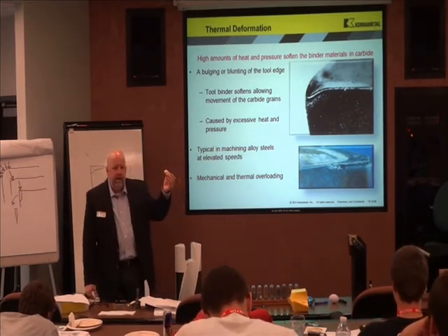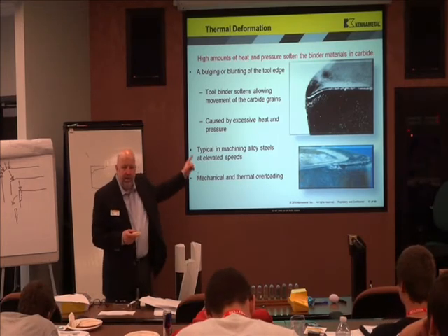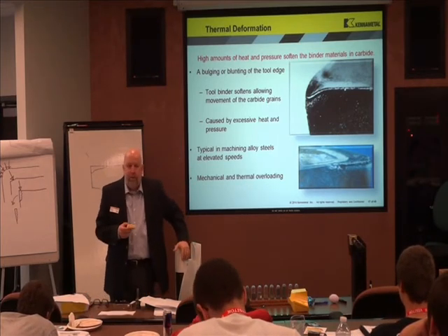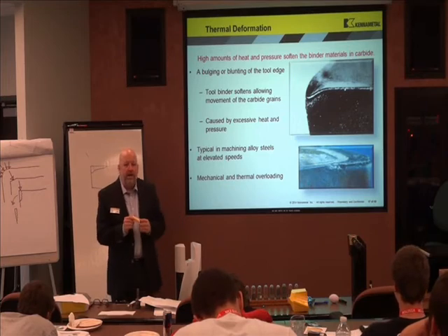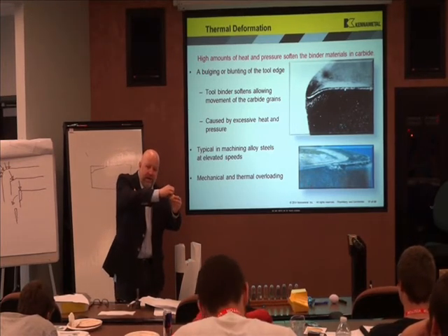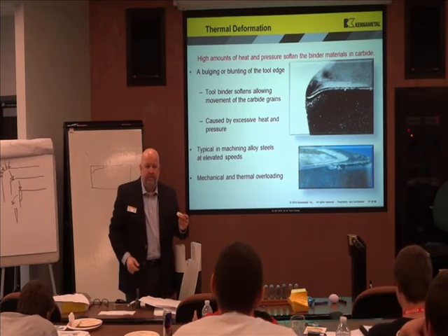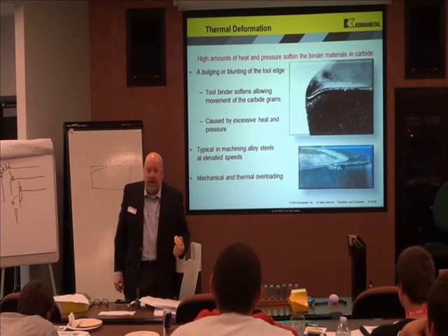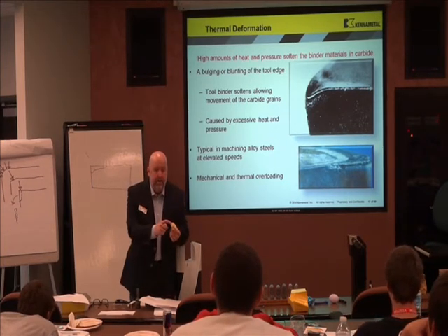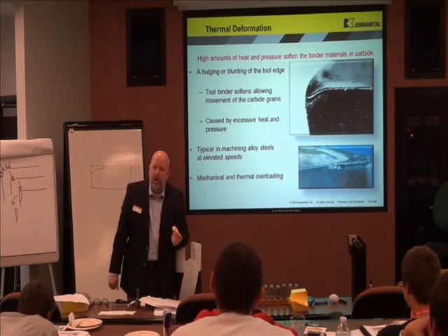Now you've got to determine, is it thermal deformation or is it broke? The way to tell the difference is if it looks like I scraped the corner off, it's thermal deformation. If it looks like a rock in a gravel driveway, that surface, it broke.